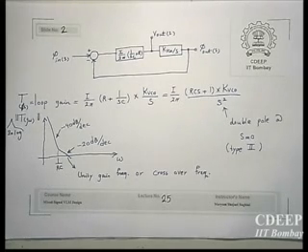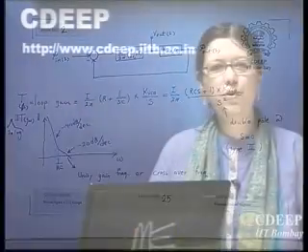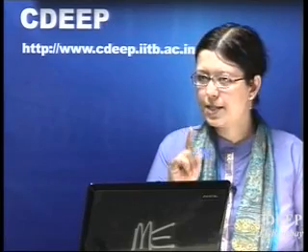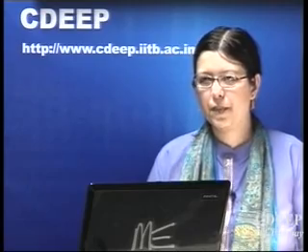Otherwise, I always have this question: this system at the beginning is unstable and we are trying to make it stable at higher frequencies. If you remember when I was talking about XOR, I told you there are 2 regions of operation, one in which the PLL is stable and one which is not. But actually that unstable region still is okay. A PLL with XOR also works, right? Of course, separate from the problems it has.